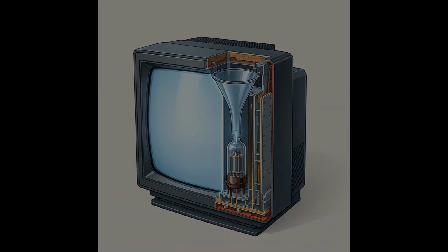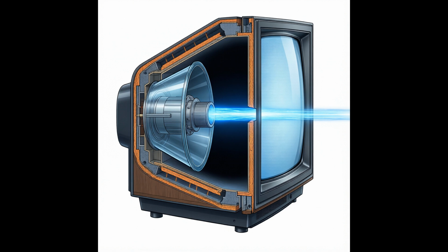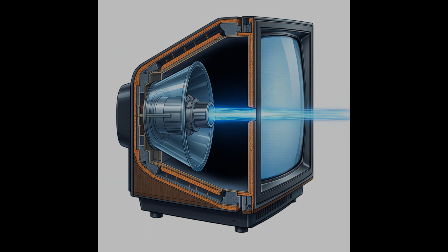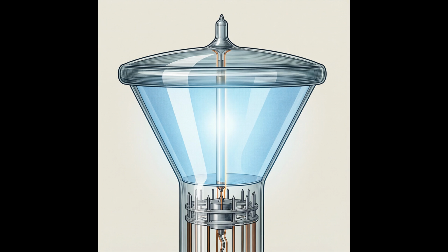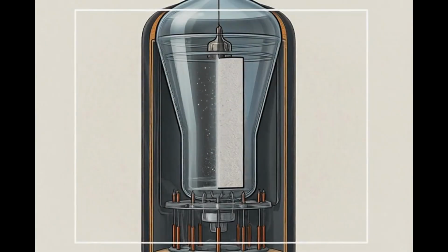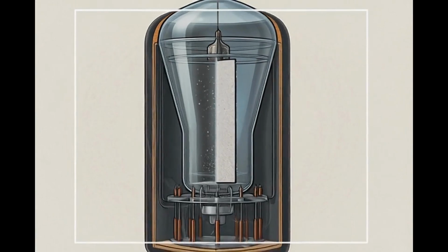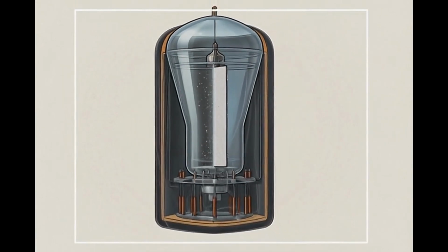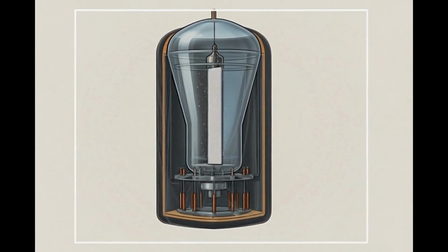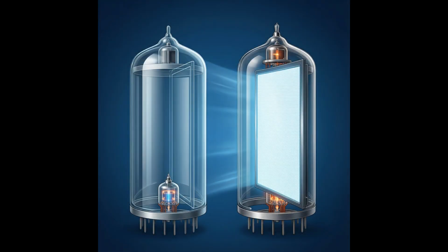To understand how old televisions created images, we must first examine the physical container known as a vacuum tube. This device requires an internal environment devoid of air molecules to allow electrons to travel unimpeded from the rear gun to the front screen. Without this vacuum state, fast-moving particles would collide with gas atoms and scatter before reaching their target destination. The glass envelope is engineered with varying thicknesses, where the funnel shape at the back reduces surface stress, while maintaining structural integrity under atmospheric pressure.